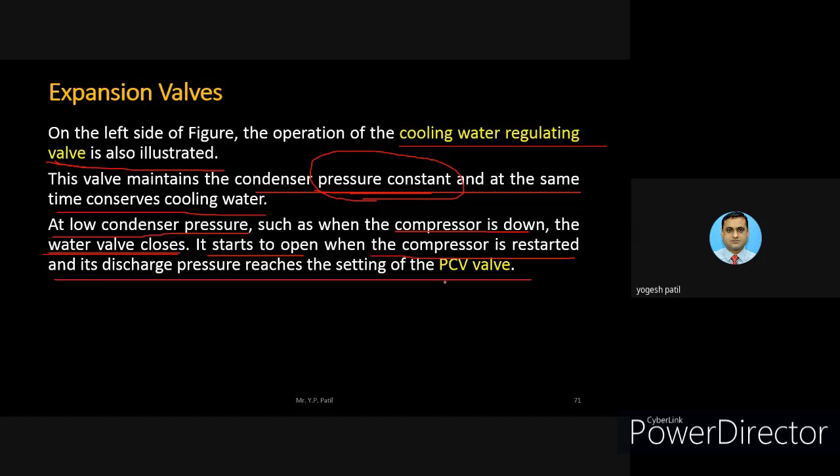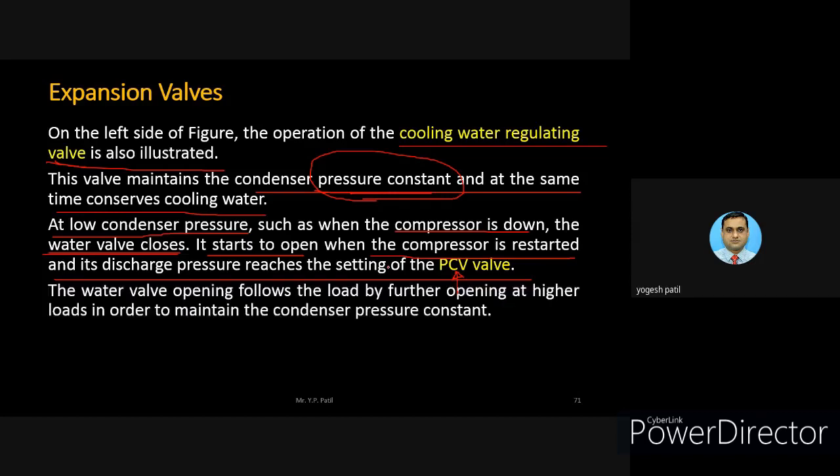Or we can say that the name is given based on what it basically controls. Basically, it controls the pressure inside the condenser. So it is the condenser valve or pressure control valve, or condenser valve pressure control, or cooling water regulating valve, we can also say. The water valve opening follows the load by further opening at the higher load in order to maintain the condenser pressure constant, right? So based on the demand of the loads, that opening can take place.